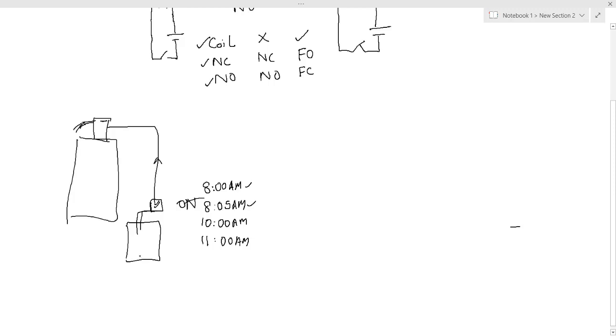What will the pump do? The pump will take all the water from the lower tank and pump it into the upper tank. Possibly the upper tank will overflow. That is okay, some amount of water was lost, but that is at least understandable. But at the same time, because the lower tank is now empty, no water can be pulled up by the pump. If no water can be pulled up, the pump will burn, right? Your pump will get destroyed. Just because you forgot to turn off your pump when the electricity went away, your system was completely destroyed.